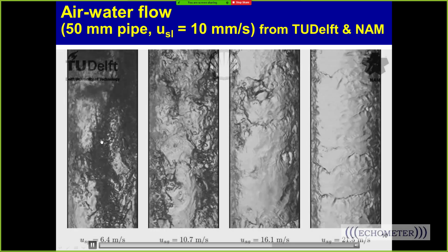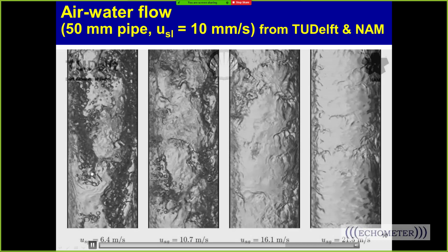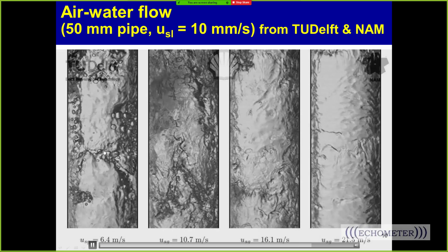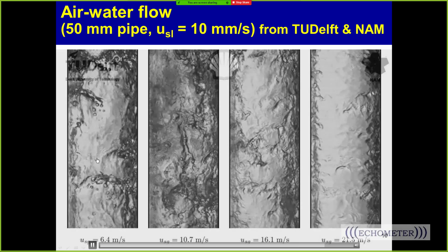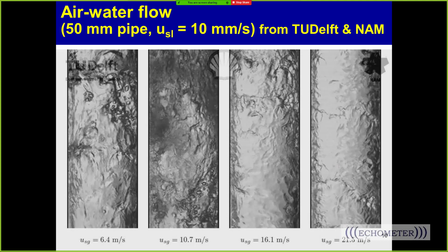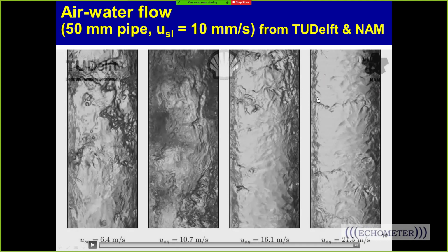But now we're liquid loaded in this case, and you can see big droplets, and the droplets are typically falling down, and those droplets are usually what Turner based his critical rate on. And people have said, oh, that's not a very good method. You should use the film velocity. If the film's going up, it's above critical rate. If the film's going down, it's below critical rate. It's a lot more complicated to calculate.